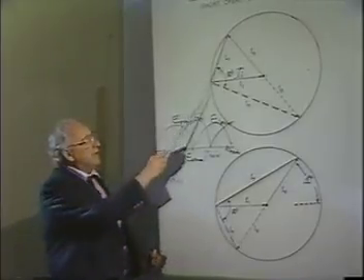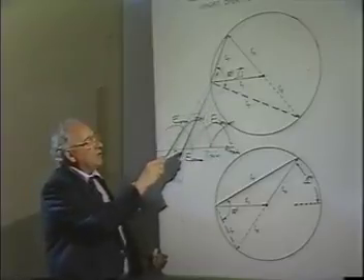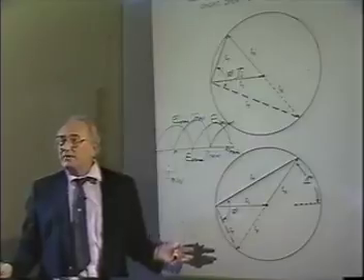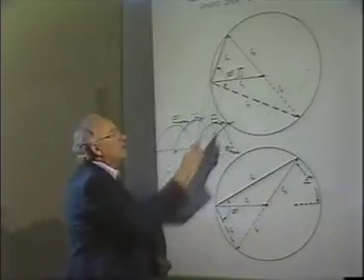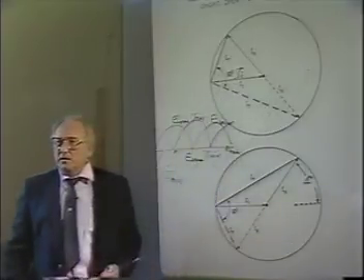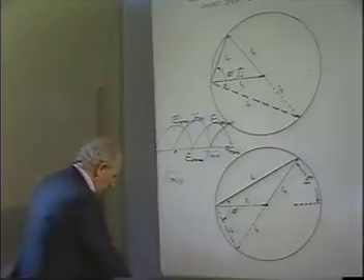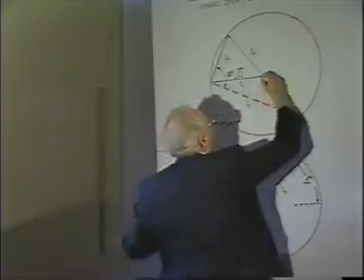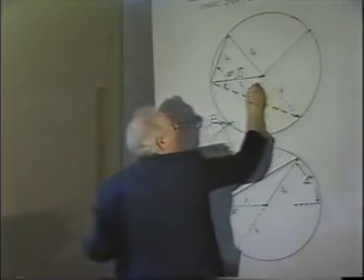So this shows you the angle between voltage and current. The total voltage to total current is always plus or minus 90 degrees if you have a pure reactive load, in other words, open, short, pure inductance, or pure capacitance. It never changes. Notice this. Suppose E sub R is over here. Where's E sub I?